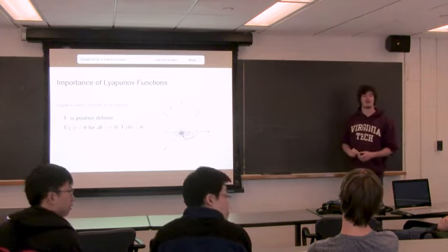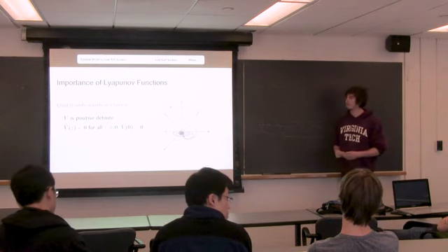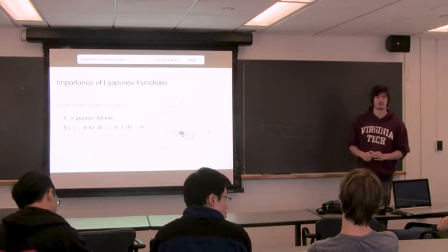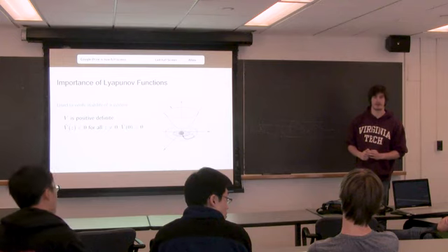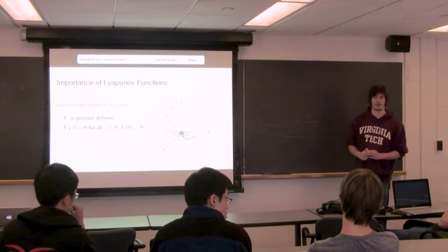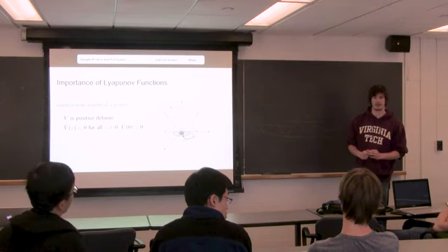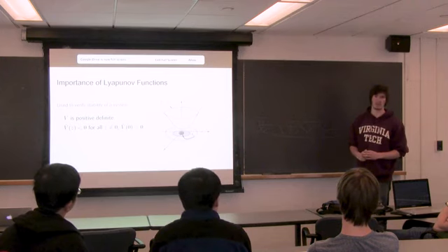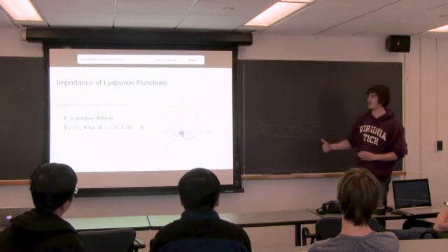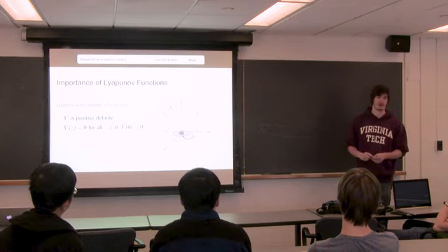I just have a basic question. So the Lyapunov function is around a stable set point, but the trajectory has non-zero velocity. So what is the point that it's stabilizing around? You can stabilize around a trajectory, which is also what the funnels do.